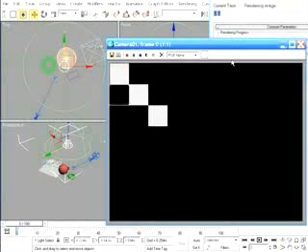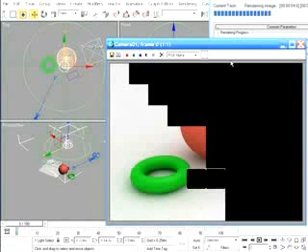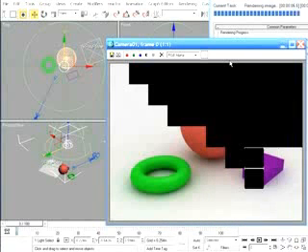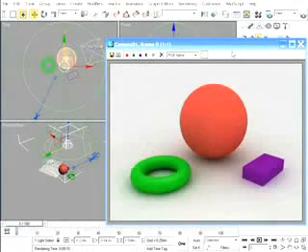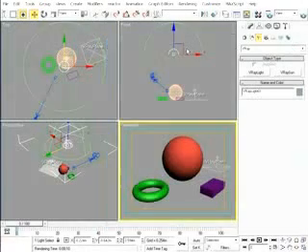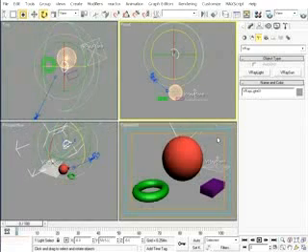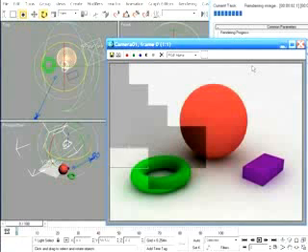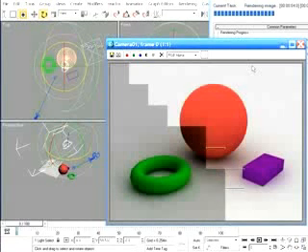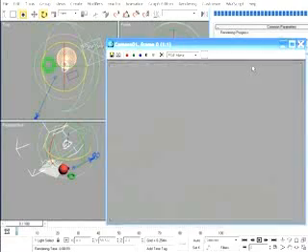So if I place the light above my objects and the light is oriented straight down, when I render, I get an orientation that allows for the maximum allowable illumination, which would simulate a rendering where the sun was directly overhead. Now if I rotate the dome 45 degrees about the local X or Y axis, then when I render, I get a reduced illumination that simulates skylight that you would have when the sun is lower on the horizon.